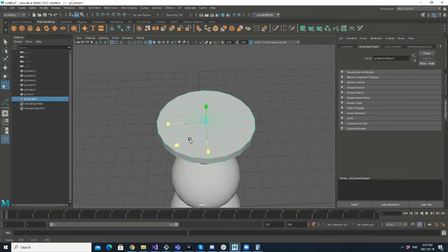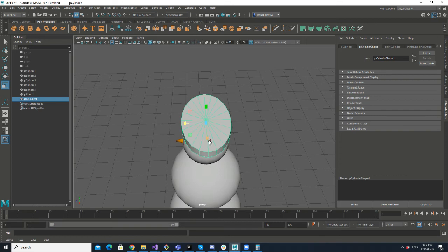So again, you see that by using this rectangle or cube here, I can scale my object uniformly along both the Z and X axis. But if you don't do it, then if I just change it along the Z axis, it's really hard for me to then go back and match it along the X axis. So that's one thing to consider.